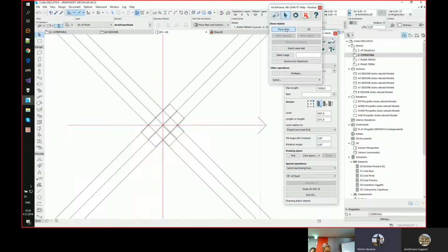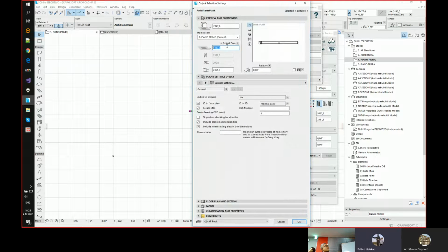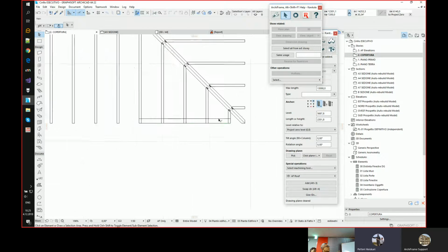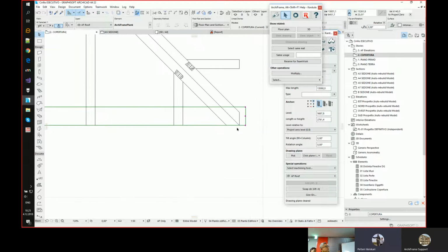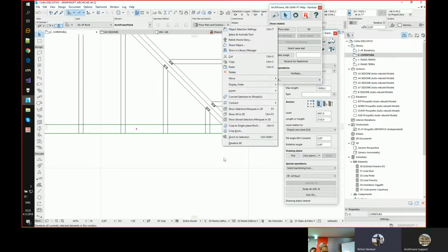And let's see this in floor plan. Unfortunately, because of the levels, it came to the wrong floor, so I'll edit this one. I preserve the level here and change the home story. Now it's here, and it will be easy to adjust it. I'll just make this corner by making this slightly too long. Or actually here I have the exact point, so I can end it here. And then I rotate a copy.